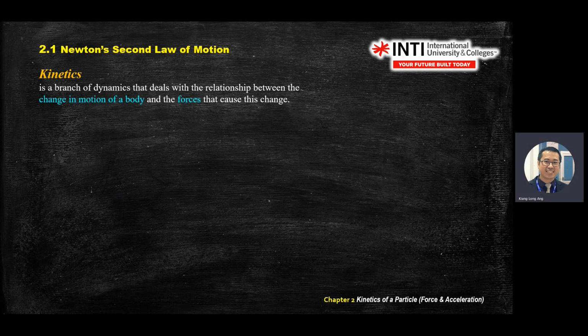Okay? So this is what you need to recall. Be careful on the left-hand side of the diagram, the free body diagram. Normally you will miss the normal force. 99% you'll get there. But most of the time you will be blocked, you will be confused on how to find your friction force. And the normal force is always 90 degrees to the body. If you have a slanted surface, your normal force always follows the surface.